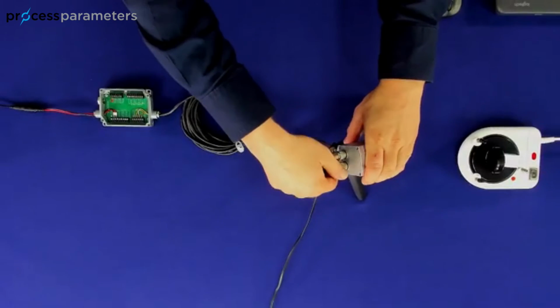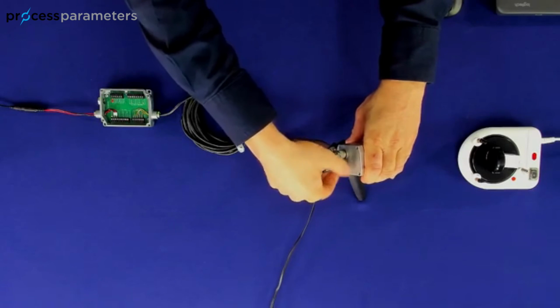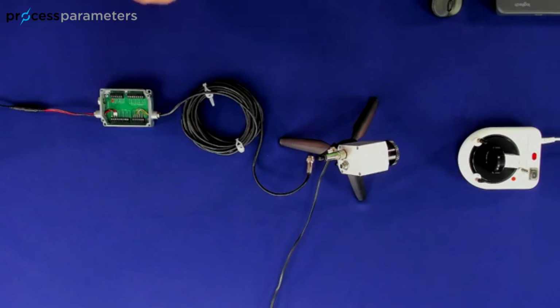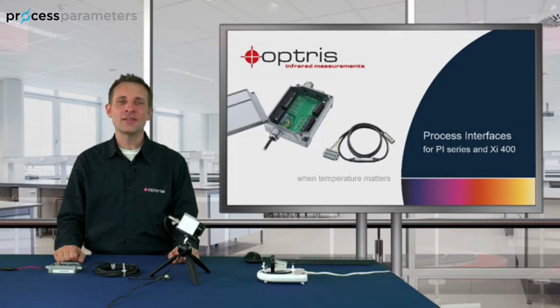I'm going to disconnect the cable from the camera now, and you can see immediately, when I disconnect, that the failsafe LED turns off. So this is a sign that you now have an interruption and you can forward the signal to your system. As we have seen before, you can use the process interface for bidirectional communication to set values and to get temperature information and alarm states.